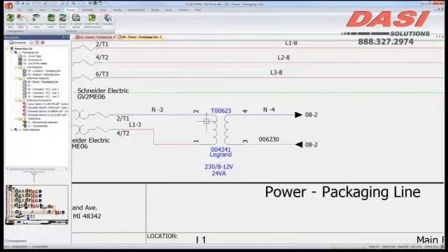Our project, of course, is based off of the numbering of the sheet followed by the row. And then for wires, it's the instance afterwards, which is 0 here. With the devices, I've set it up so that you only see a blank if it's the first instance, but it would have an A after it otherwise.